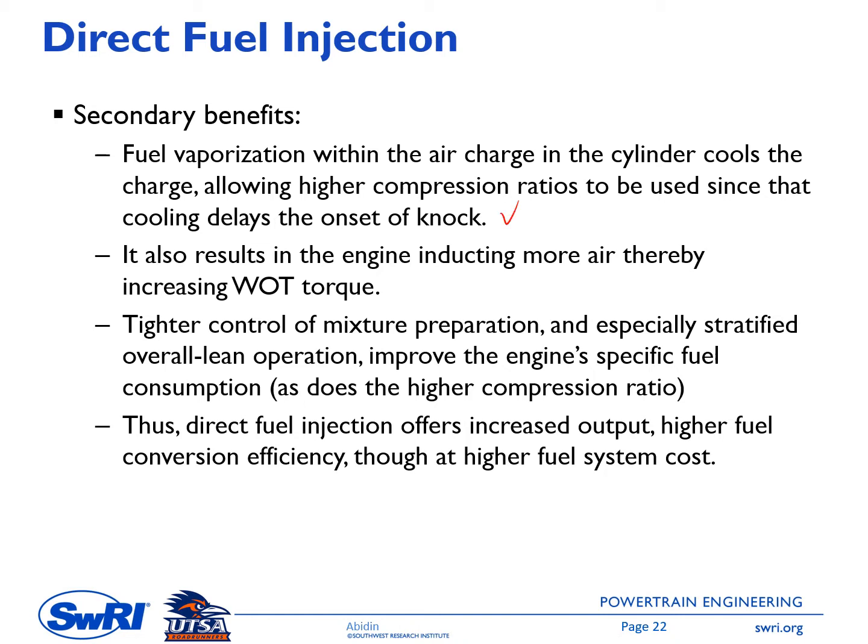Knock is strongly dependent on the mixture temperature. So if we can have a lower temperature, it will lower the propensity to knock. One way to reduce the knock propensity is by having a cool mixture at the start of the compression or during the intake stroke.